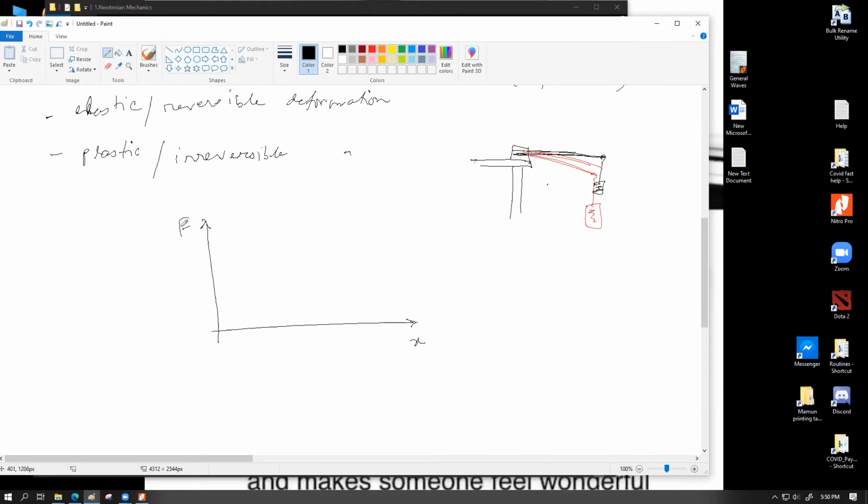So if we plot a graph of force versus extension, the typical way most materials behave, I'm saying most because there are some other differences for polymeric substances, which we're going to cover a bit later, for a pretty significant part to begin with, they give us a pretty beautiful straight line. So let's say something like this. And this straight line represents that the further you apply force, you're going to have a proportional increase of extension. So more force, more extension.